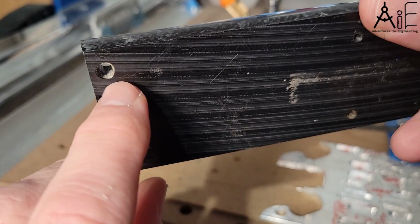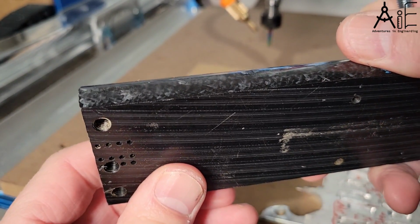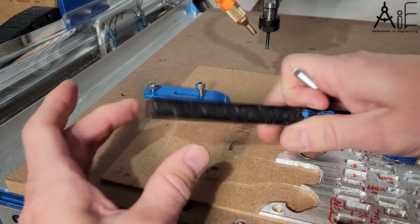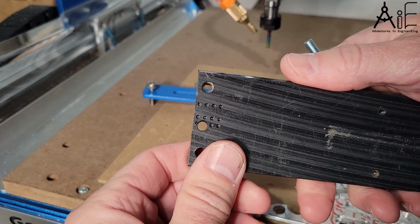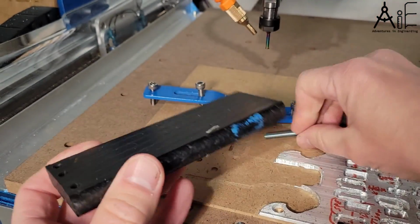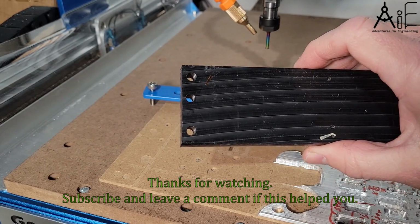Got a little bit of sawdust up in there from the drilling down into the spoil board. But that's okay. Easy to clean out. And you can always do this over a gap, or raise up your piece so that you don't have to drill down into the spoil board. Anyway, nice looking threads, and they're exactly as advertised. So there you go. That's how you thread mill with FreeCAD and your CNC machine.